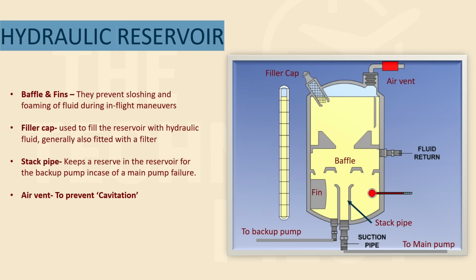In a hydraulic reservoir, these are the few components that you have to go through. The first one is your baffles and fins. These are your baffles and these are your fins. What do baffles and fins do? They prevent the sloshing and foaming of fluid during in-flight maneuvers.